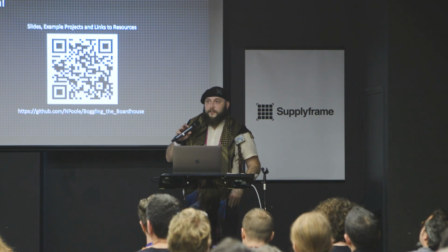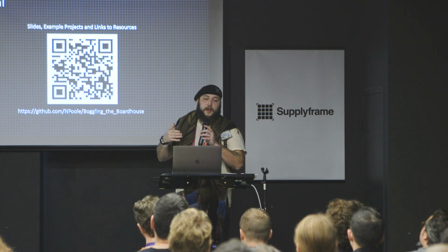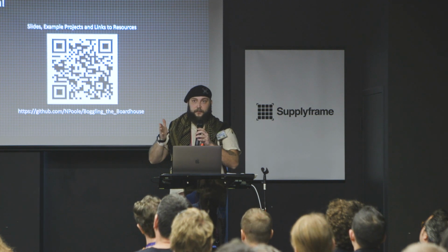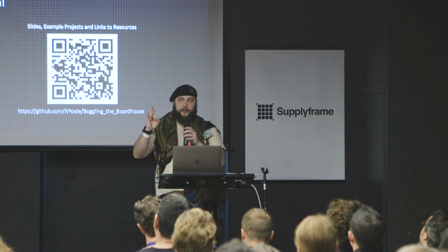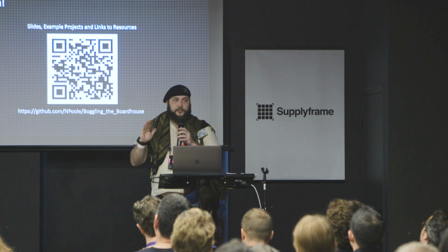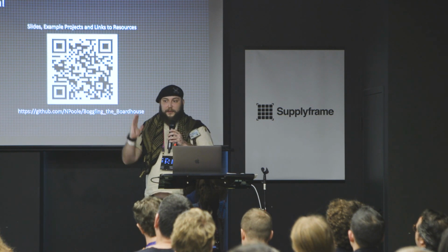There are a couple ways you can go about attaching multiple layers when they're stacked directly against each other. You can either use SMD pads and then castellated connectors. Castellation, if you're not familiar with that, is basically you make a plated through hole and then you mill half of it away, and you end up with a plated edge. And the cool thing about castellations is they don't cost extra the way that edge plating does.